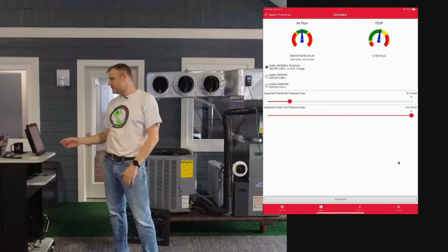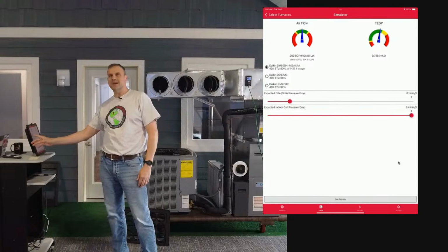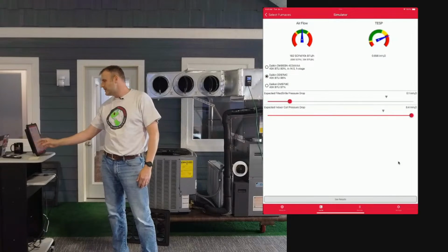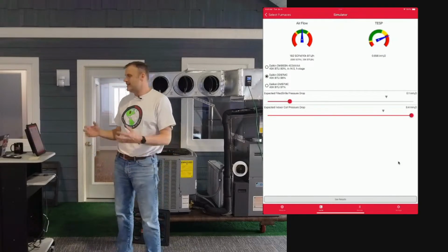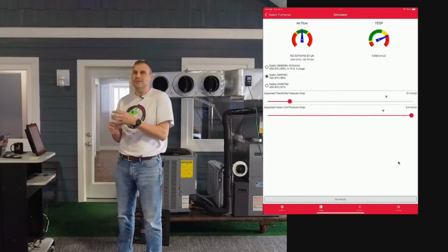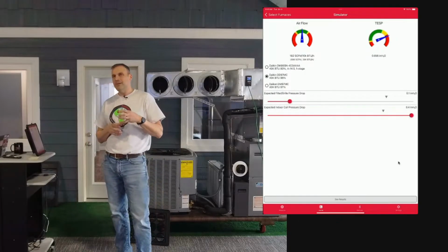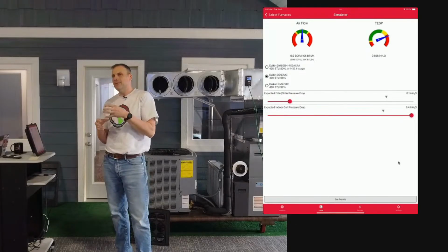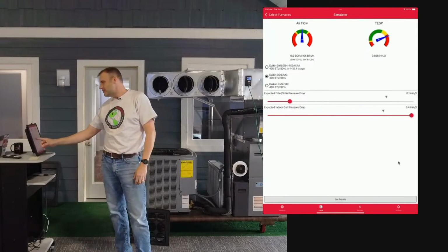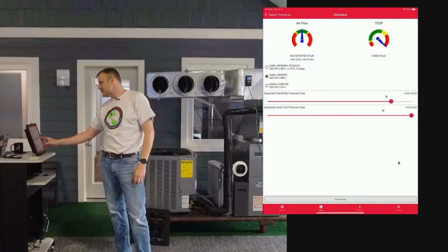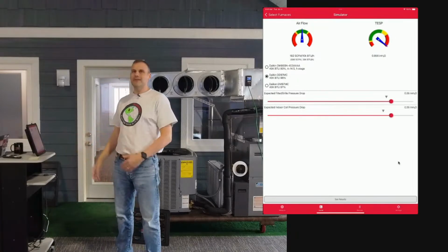All right, so let's say we have different furnaces to choose from. That furnace is not what we want, so we just touch the second radio button. Boom, we go to this furnace. You'll see that the gray triangles have moved. Those are the benchmarks for the existing pieces of equipment at the new design flow for the next selected furnace. So we move that over to that triangle, and that's where that furnace lands out.